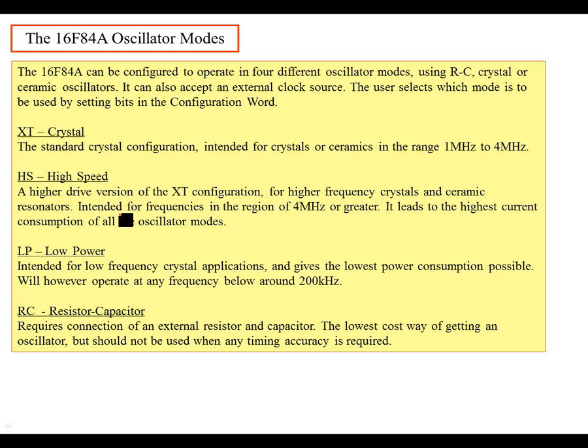Now the crystal modes, like we've talked about before, are very stable because they're dependent upon the cut of the crystal. You basically have the piezoelectric effect, which says that if you put a voltage across the crystal, it's going to deflect mechanically. The corollary of that is if you deflect a crystal, there's going to be a voltage across it, made by just simply physically deforming it. So once you put a voltage across it, it starts to vibrate, and it tends to keep vibrating if you put a voltage across it to reinforce that. So you wind up with this sustained oscillation. But what you need is an amplifier or something across it to keep the voltage always present.